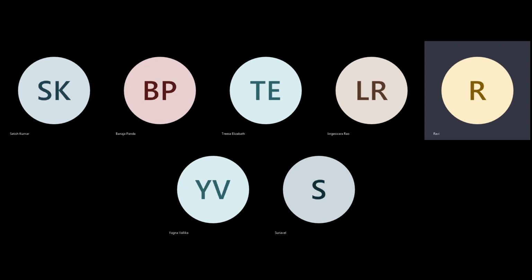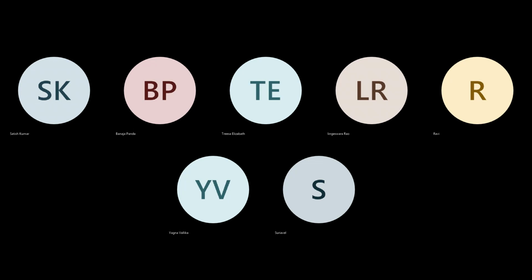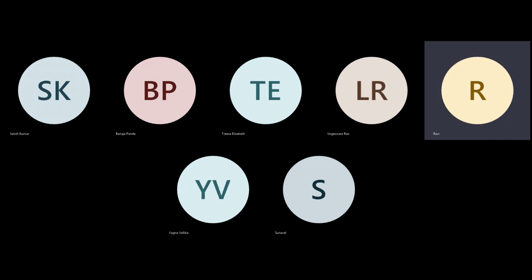It's okay to take 2 days and just do coarse placement. You should not go for complete placement initially. You should just do coarse placement, module placement, to see whether the modules are sitting properly as you discussed in the design. If that is not coming out right, there's a problem.